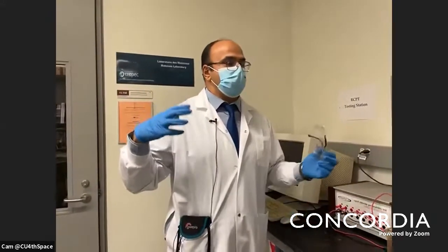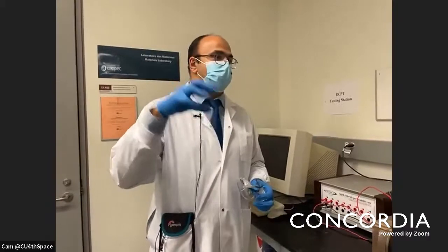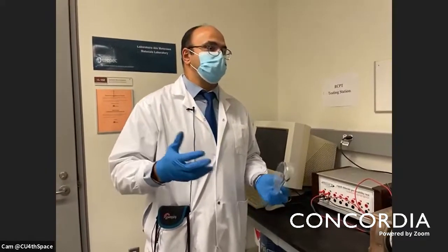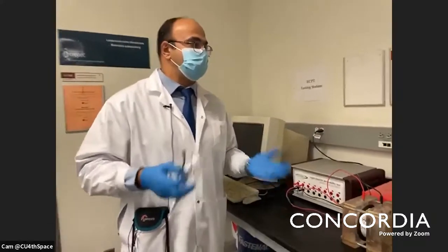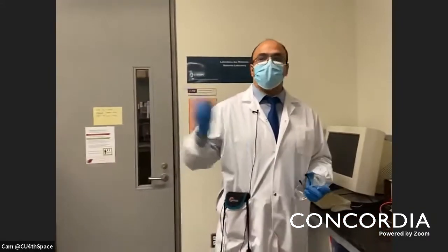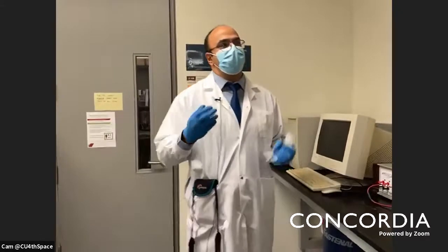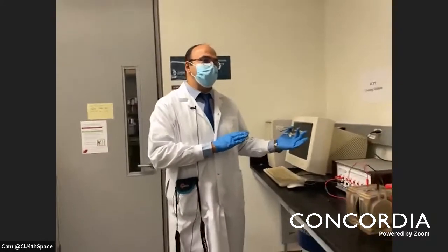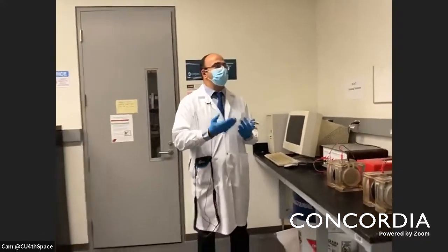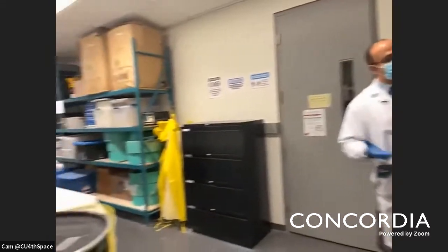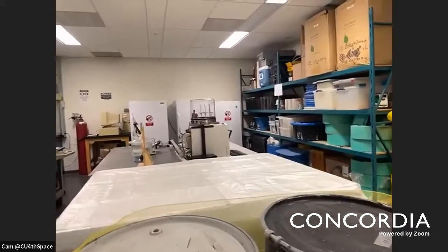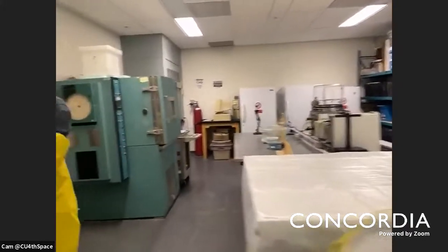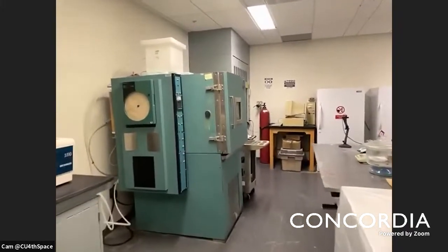Also, we have standard tests where we can insert our samples, for example, in a sulfate solution to simulate what's happening if we have attack by sulfate. And using the environmental chambers, we do not replicate exactly what's happening outside, but we accelerate it a little bit. So we expose it to more severe conditions than outside, inside the environmental chamber. And as you can see, the environmental chamber is programmed. You can change the temperature, you can change the relative humidity.